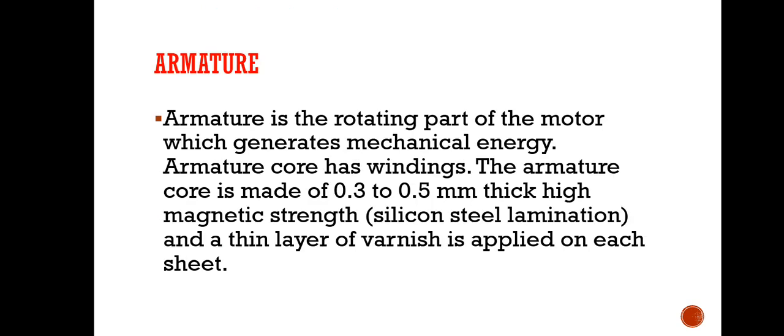Armature. The armature is the rotating part of the motor which generates mechanical energy. The armature core has windings. The armature core is made of sheets 0.3 to 0.5 mm thick, of high magnetic strength, and a thin layer of varnish is applied on each sheet.